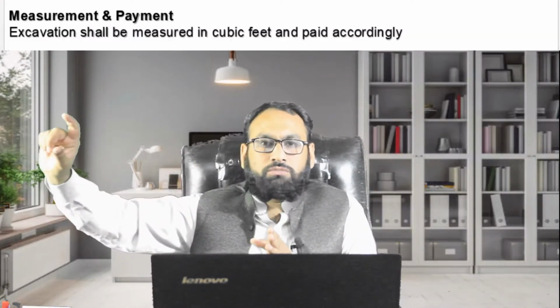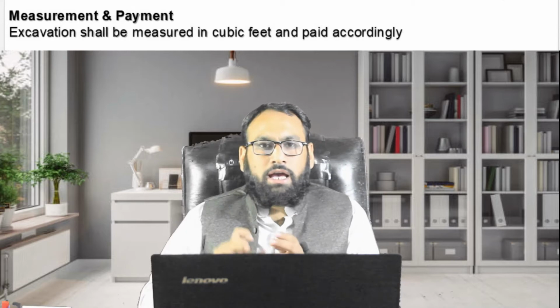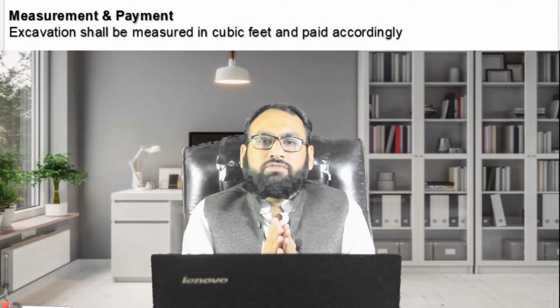One thing is very important: the measurement of the excavation must be in cubic feet or cubic meter, because we take the length, the breadth, and the depth of the excavation. We multiply all these three measurements, and this gives us a value in cubic meter or cubic feet.